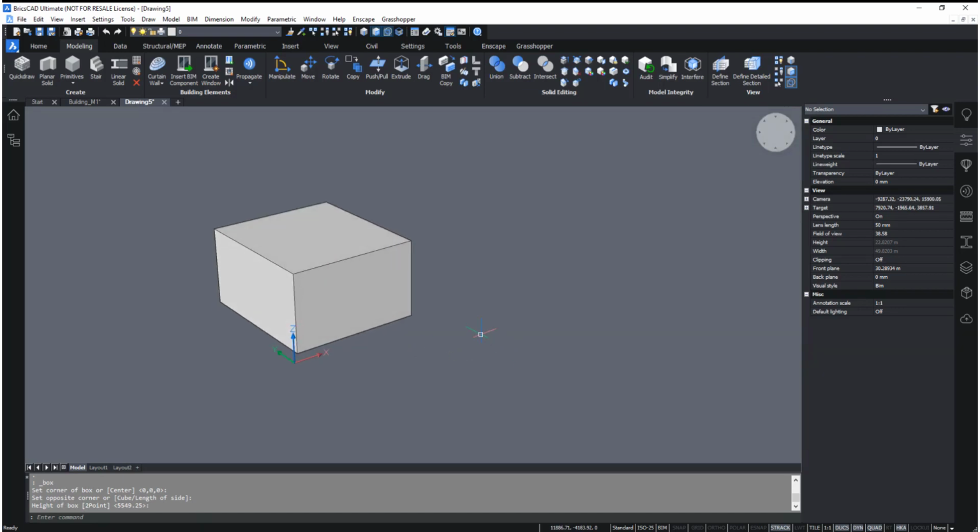Now when we hover the cursor over one of the faces, the quad displays as a single icon, which is the most recently used tool with this entity type. And if I click on that, we can see, in fact, it does say solid face now instead of no selection. If I want to launch the most recently used tool, I can just left click or move the cursor over an icon that I do want. So we'll just go ahead and use push pull, and now we can use the push pull icon.